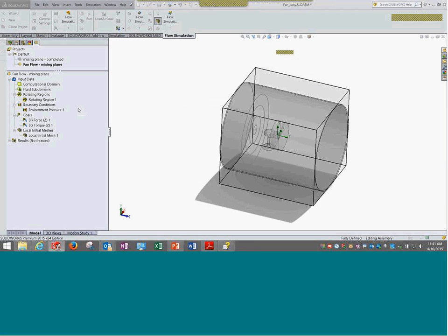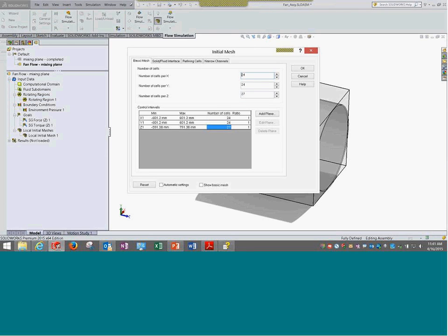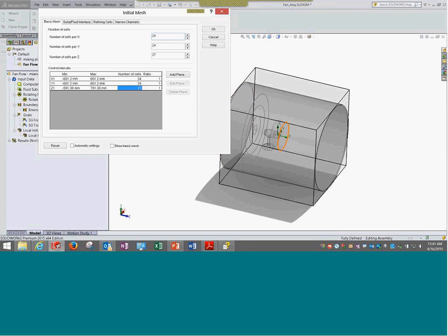So typically for a rotating region, the mesh is very important. You have to capture the rotation accurately. The simplest thing which I tell the user is to use the local component that has been created to represent the rotating mesh. You can use the same component to simulate the quality of mesh that you want to create. Okay, so that can be done.